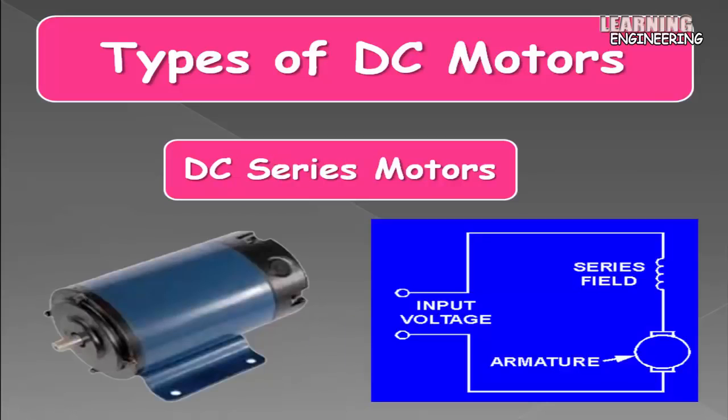DC series motors. A shunt DC motor connects the armature and field windings in parallel, or shunt, with a common DC power source. This type of motor has good speed regulation even as the load varies, but does not have the starting torque of a series DC motor.